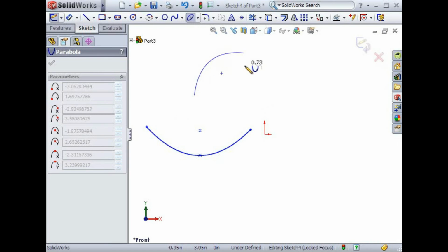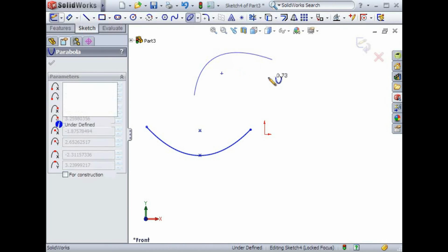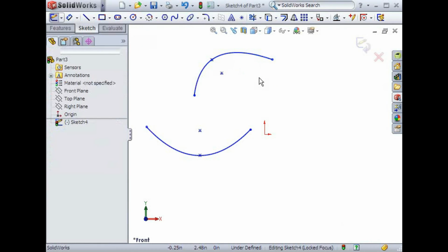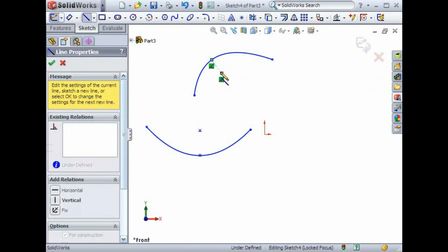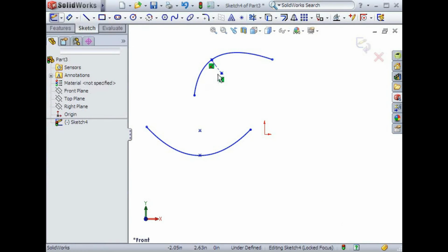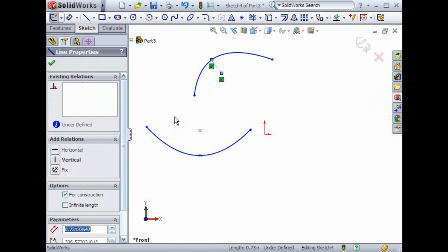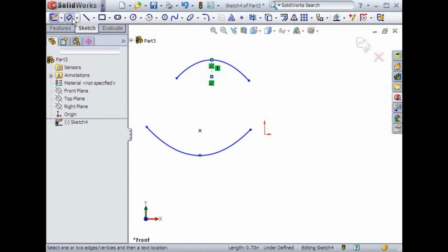finish. Defining a parabola really depends on what you're trying to accomplish. One thing I would recommend is adding a center line from the vertex to the focus. This gives you a way of establishing a direction for the parabola, such as making the line vertical, and it provides a convenient place to add a dimension. This dimension will control how wide or narrow the parabola opens.